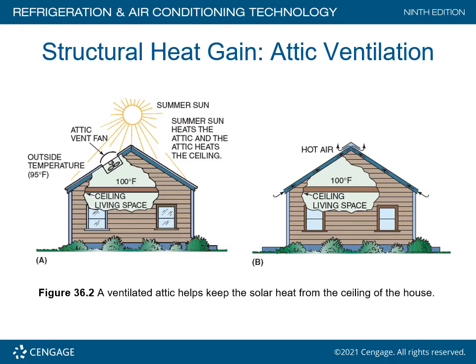The problem with this is the heat becomes entrapped, vents get clogged up, and a lot of times there's not enough vents inside the attic structure to relieve all the heat out. So in some cases, and I'm thinking older construction, I'm not concerned about new construction. Older construction, this is more apparent and needs to be addressed.